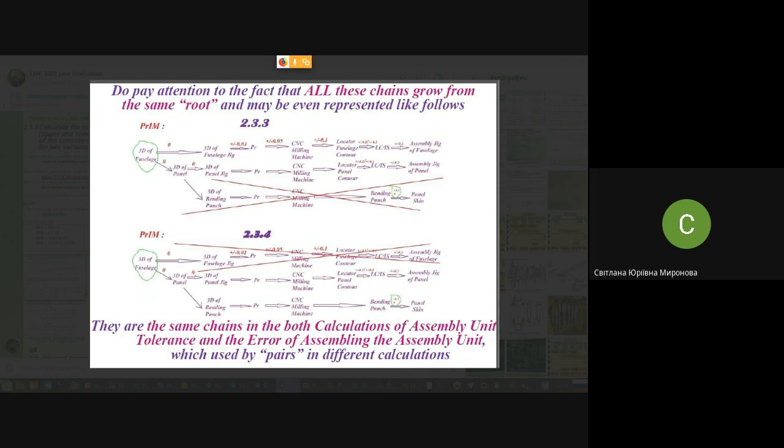In order for all the cubes to fit in the box without any problem, the demands for the cubes, for these components, are more strict than the demands for the box itself. And you are going to put your unit, your rib or spar or something like this, into the jig of the wing.